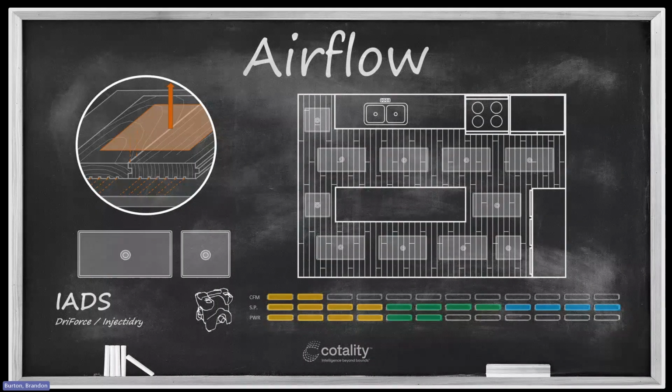On a hardwood floor where there has been a significant amount of cupping and expansion, generally you're going to start to see some areas between the boards where it's very obvious that air is going to move down pretty readily because of the distortion that's occurring on the floor. It's also an indication there may be some permanent damage on the floor. Not a topic we're going to dig into today. Definitely had an episode on that last year where we dug into that pretty deeply. All right, so that's the second point I want to make: the distance between these mats, perpendicular to the boards, the length of the floor, anywhere between 2.5 and about 4.5 feet, depending upon the tightness of that floor.